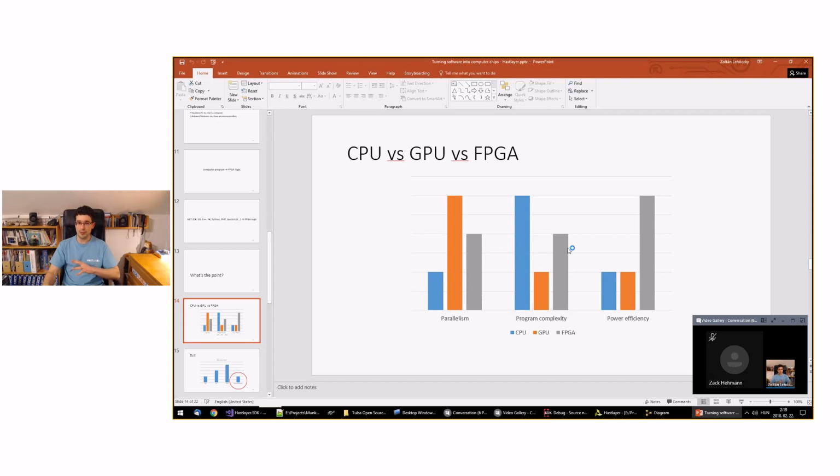But the complexity of programs and code that you can run there is lower, because most of the high-level synthesis tools that you would be able to use, including Hastlayer, are not available for that. And the biggest drawback here is that the cost of ASIC development is at least 2 or even 3 orders of magnitude higher than FPGA development. They say that if you want to begin ASIC development, you need a couple of years and a couple of million dollars.